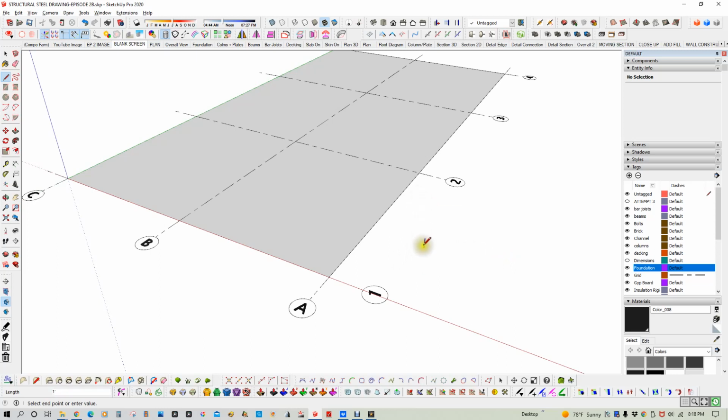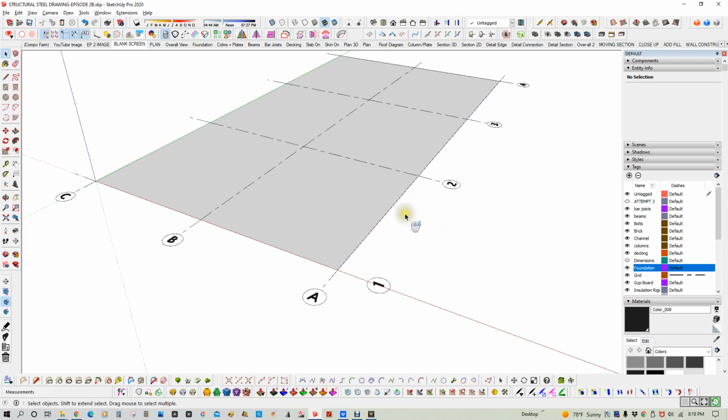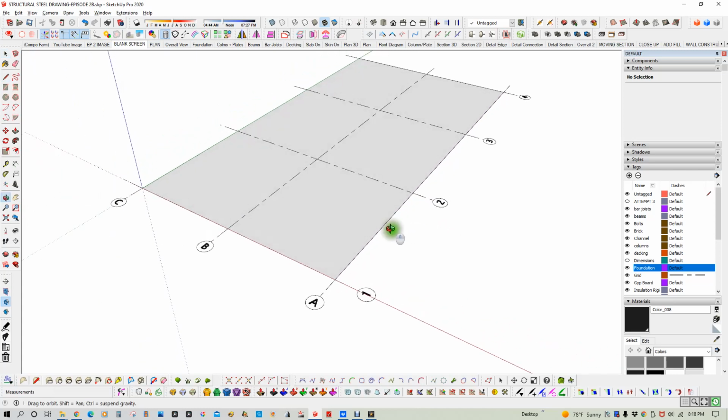The down arrow key doesn't make a lot of sense here right now unless I was holding it, putting the line onto something. I use pink. See what happens is if I rotate through it, it cycles. That's perpendicular to and parallel to. So all the arrow keys do something with lines. They create an inference for you to stay on axes.